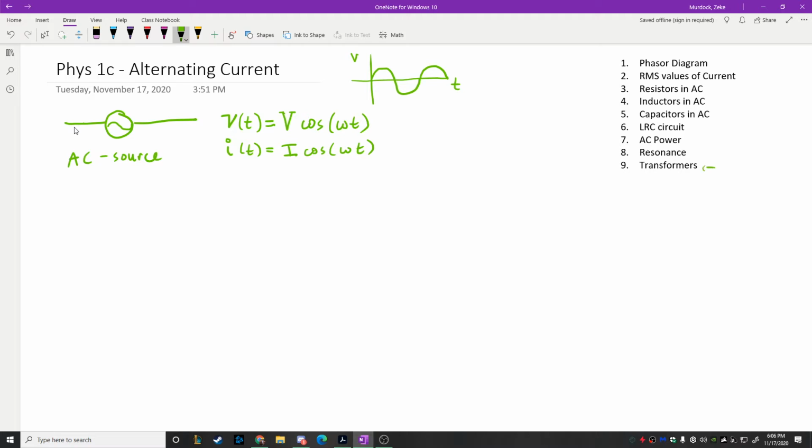But I'll just say this way, that alternating current works really well with transformers, and it's one of the main reasons that we can produce power in very distant locations and then pump that electrical power to wherever we want. A good example is right here in Southern California, where we get a decent amount of power from the Hoover Dam. If any of you have driven to Las Vegas, you'll know that it's not close. That power is sent over transmission lines at really low current, so that you lose less energy in the process.